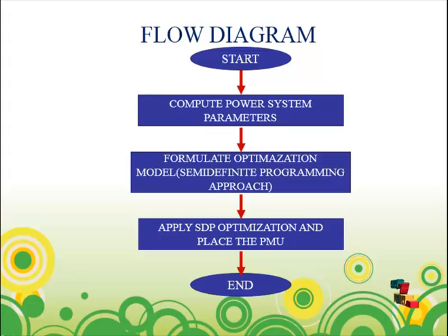Generally, a synchronous phasor is a phasor that is time stamped to an externally precise and accurate time reference. Basically, a solid state relay or digital fault recorder with GPS clocks. Synchronized phasors provide a real-time measurement of electrical quantities across the power system. The resultant time tagged phasors can be transmitted to a local or remote receiver at rates up to 60 samples per second. It continuously measures voltage and current phasors and other key parameters and transmits time stamped messages.